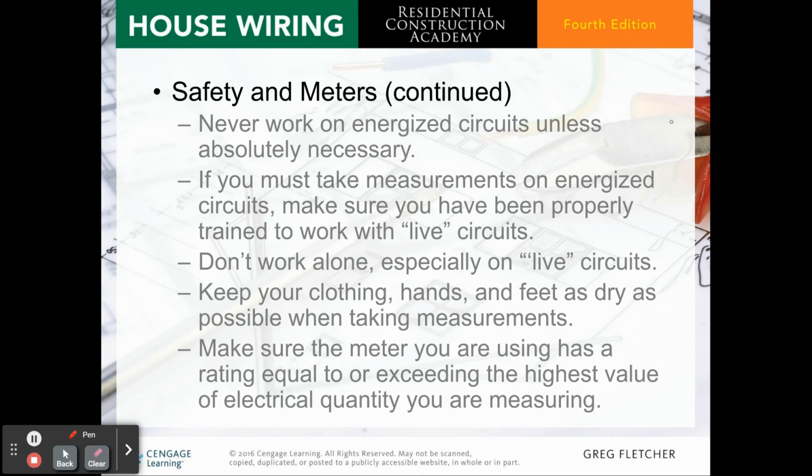Don't work alone, especially when working with live circuits. Keep your clothing, hands, and feet as dry as possible when taking measurements. Make sure the meter you're using has a rating equal to or exceeding the highest value of electrical quantity you are measuring.